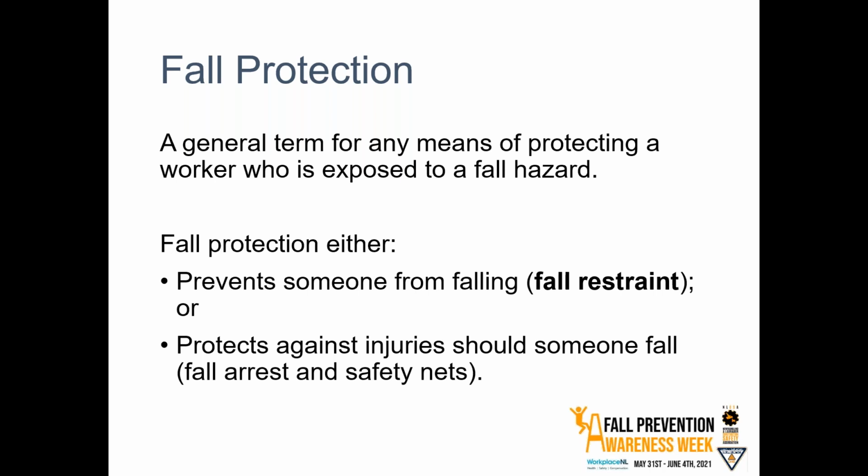Now, before we go much further, I do want to mention that I will be using the term fall restraint just to keep things consistent here, but a lot of people also use the term travel restraint, similar to fall protection being called harness training and all these different things. Travel restraint and fall restraint can be used interchangeably. I'm just using the term fall restraint here because really what we're trying to protect people from is a fall, whereas travel restraint can also be used in a lot of other different scenarios.